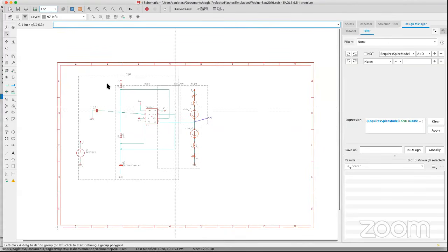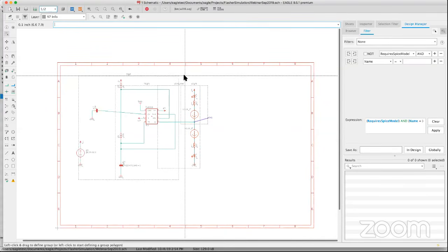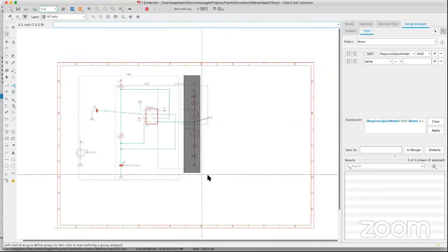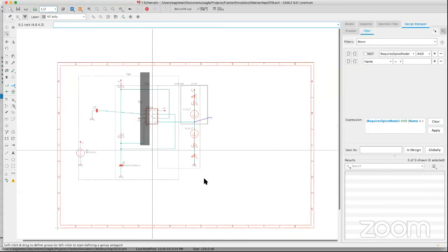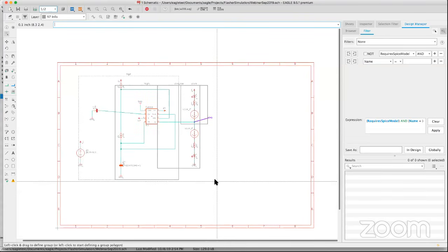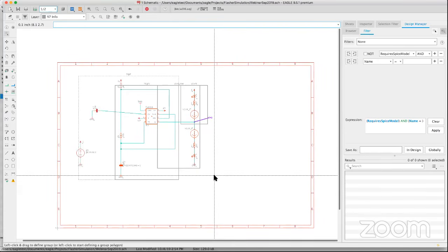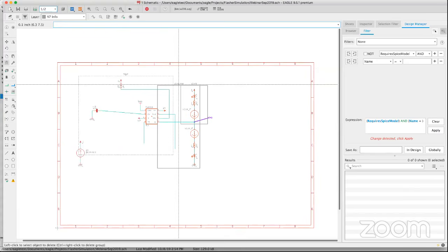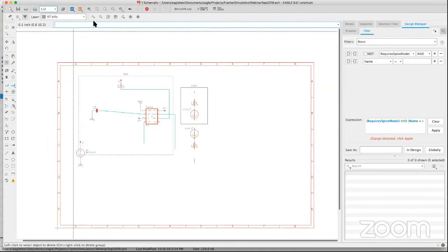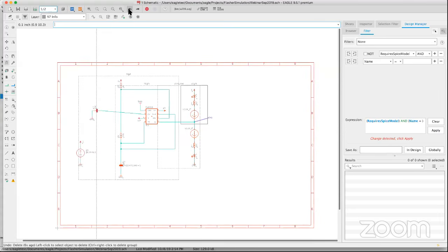It's not behaving the way I expected it to behave, Jorge. So I select all my assets that I wish to use in my group. Remember, it can't handle persistent groups. So do I need to delete them? Yeah, you have to clear the persistent groups because right now it can't deal with them. That's why it's not working. Get rid of my persistent groups. Oops. Remember, you want to clear the group, not delete it, because if you delete it, you'll trash everything that's in it.